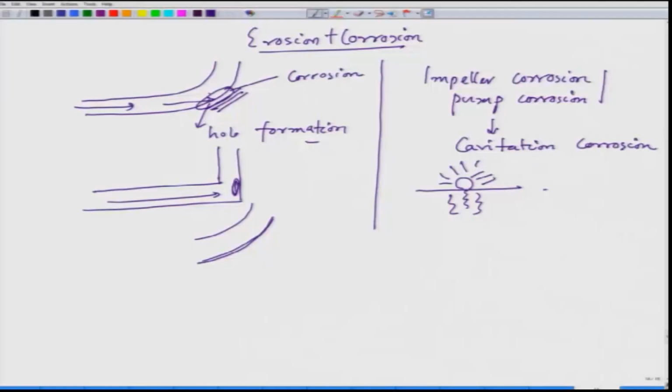Once we have deformation, that means it is becoming active. Once it becomes active, the corrosion rate is also increasing compared to the region where the bubbles are not forming, and then there is prolonged corrosion of that region. Because of this bubble collapse, there is a small dent, and once we have a small dent, that will nucleate another bubble around that region.